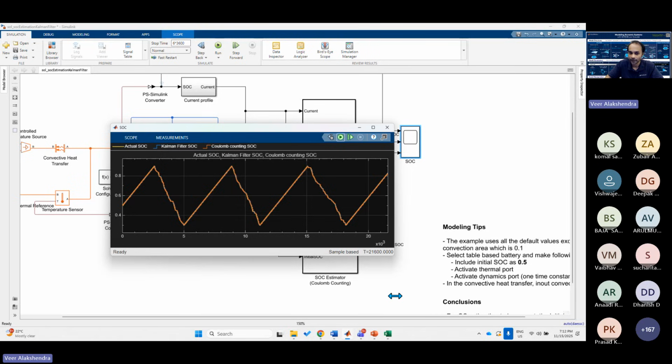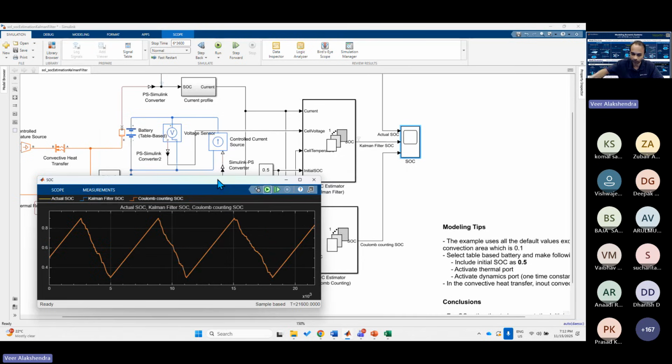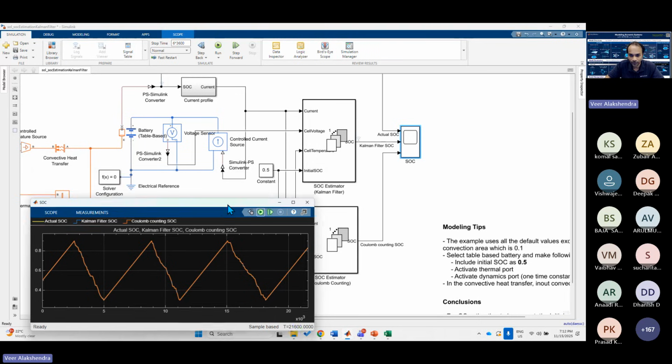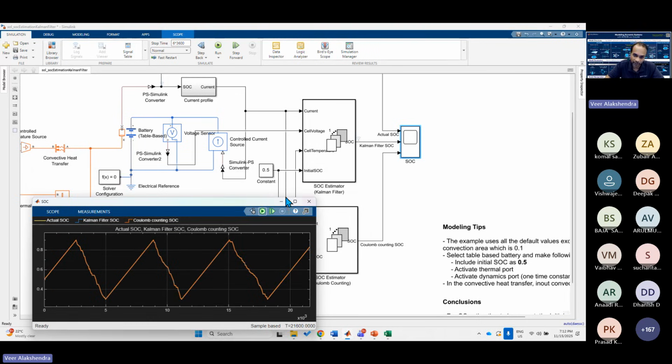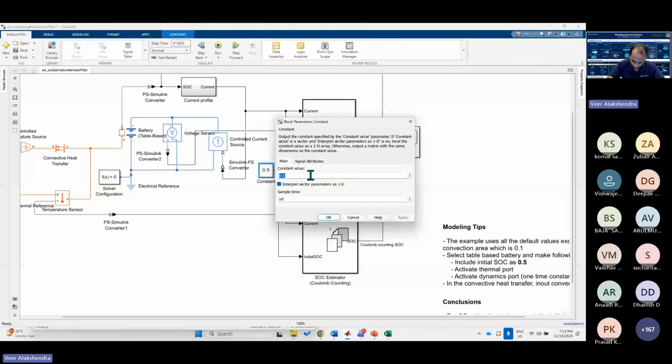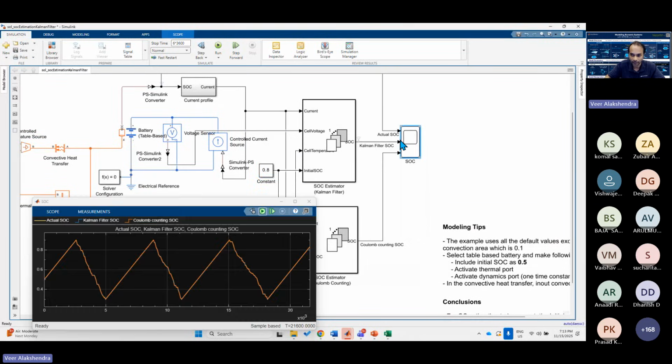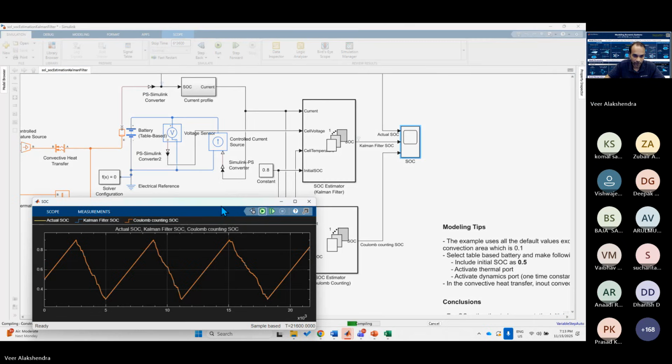The problem is that in real scenarios, when the vehicle is moving and you have some noise, the effect of the noise will be the same and it won't try to converge. Whereas your state of charge estimator using the Kalman filter will take that noise into account and try to converge and reach the actual state of charge. So for example, I just put 0.28 back over here and simulate it again, and this is what you get.